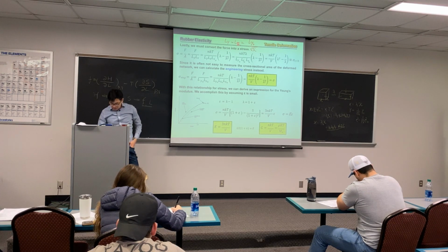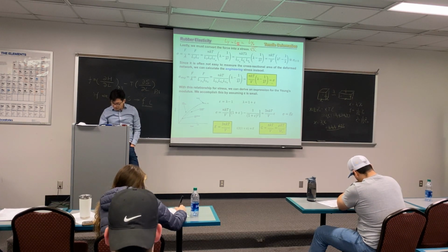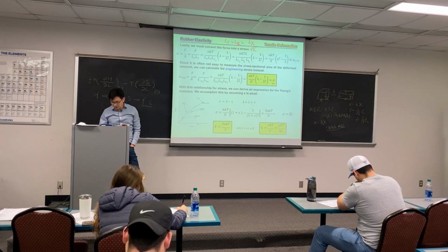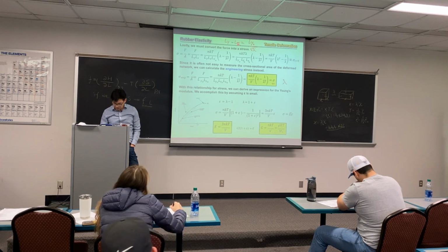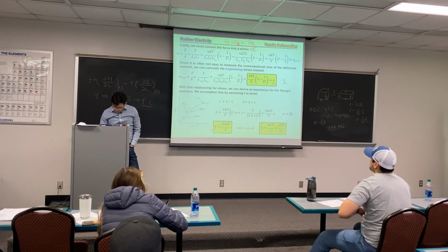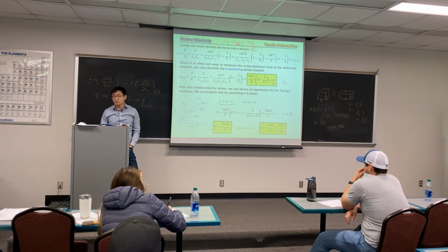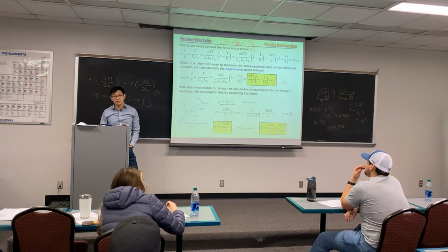You can also get some more terms. If we know the stress and we know the lambda, we can actually calculate the modulus out of it. You can apply this equation. Draw ratio minus 1 will be your strain, right?